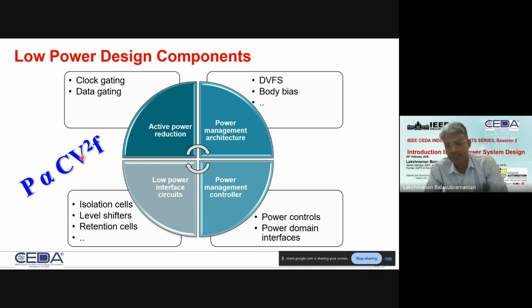In addition, there are technology dependencies, which I won't get into the details of in today's presentation, about the type of devices or the specific type of transistor types that we are using, and the technology with which they are processed and fabricated. They will have a very specific sensitivity to their maximum frequency of operation, right? Most of the time, with a given technology, if a device goes to a lower voltage of operation, its performance deteriorates. It cannot operate at the highest possible frequency, right?